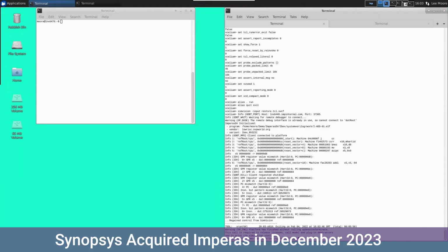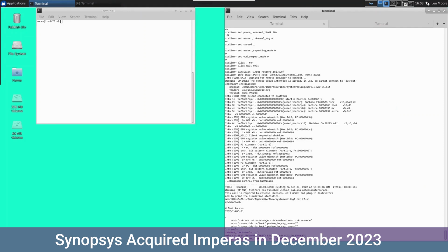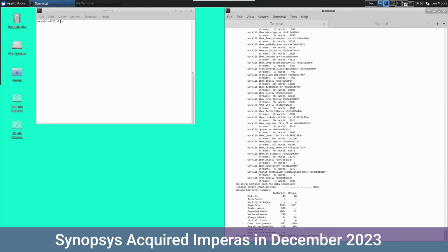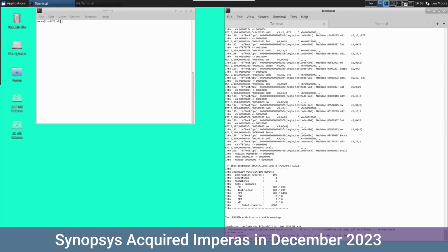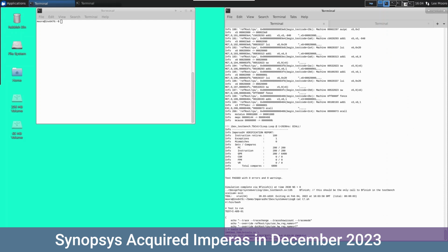And the last script I have here is pretty much similar to what we started off with, with the tracing turned on. I'm just going to run that to see this again run through to the end with all the tracing. What that's done, just to show, is we've turned off the RTL error, so we're not seeing the differences in terms of the add instructions misbehaving inside of the RTL code that we're executing. So hopefully that's given a good introduction as to how we can describe and communicate across to ImperasDV the operation of our device under test.